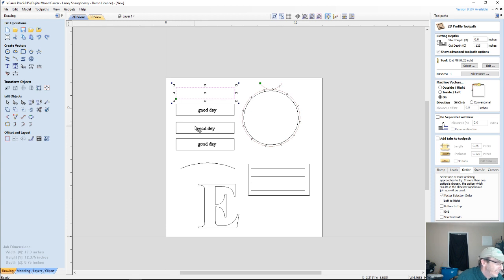It's not just willy-nilly clamping a bunch of boards on my table, hoping I got my spacing right and everything. I have a jig that is spaced for certain size boards that I just drop them into these little pockets and things, and so that way that known location is the same spacing and everything I have drawn in my design.